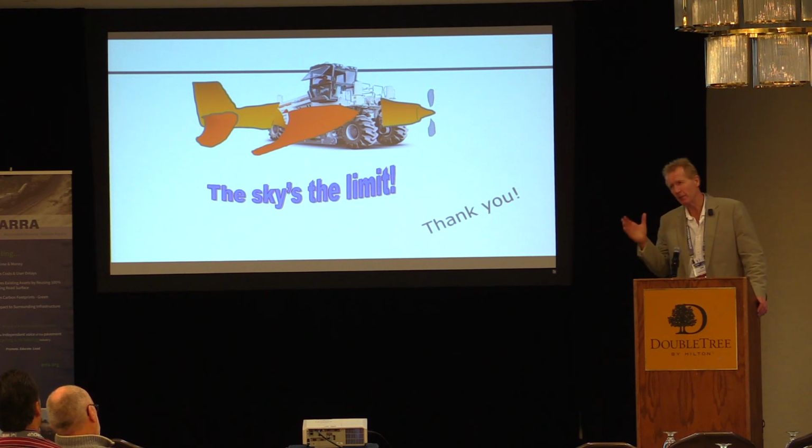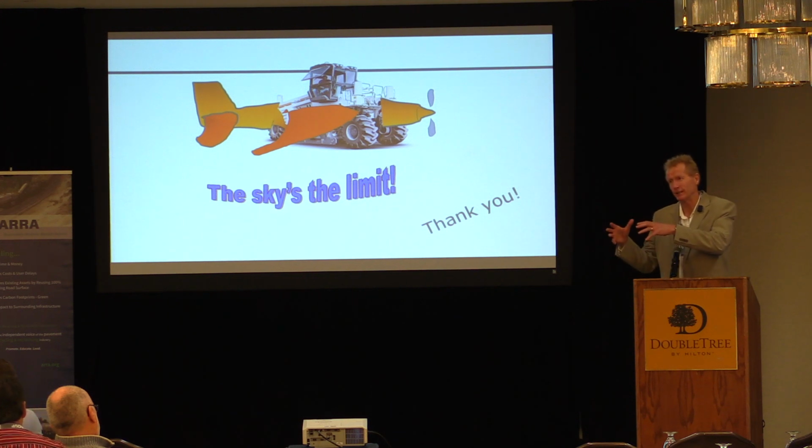I think in some extremes there are some adaptations that are needed, and we're seeing that with some of the 100% RAP mixes, particularly if they've got soft binders. One needs to take other considerations, because you start moving into, instead of being non-continuously bound, it's almost like a cold mix asphalt. And we see that gyratory compaction works very well for those mixes.